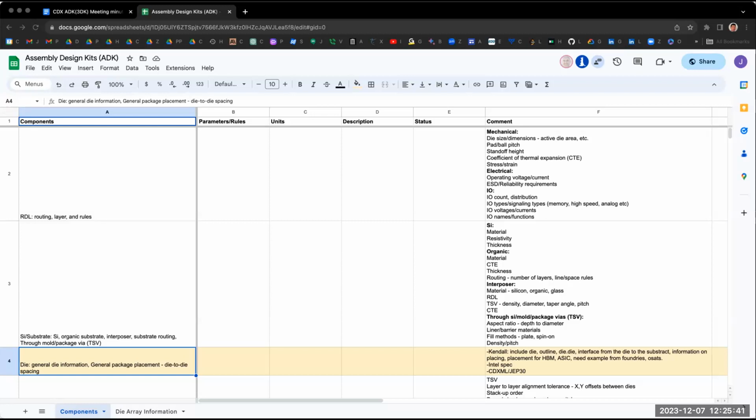Yeah, I just mentioned that based on the different product, we will have the general design rule, including maybe the bump dimension and the related distance, and maybe the capacitor size, and the heat sink, and the related distance is very important to define the rule. So that is a little bit different, but we do want to encompass that.